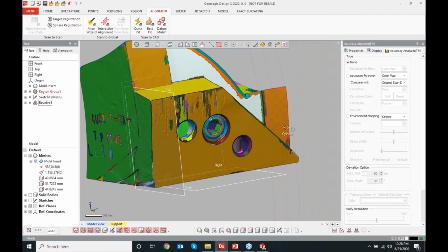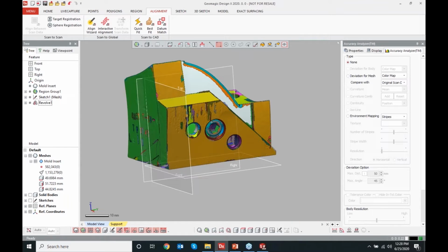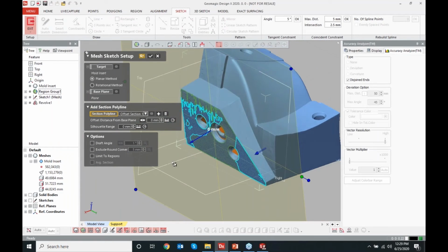If I want to be a little bit more quick, since we're in the interest of time here, and I want to let Matt do his thing in a few more minutes at least, and show you some more organic modeling, I'm going to do this the more quick method, where these regions that we've extracted here can basically be used as reference geometry without me creating and constraining reference geometry. So I can right click that region and place another mesh sketch on it.